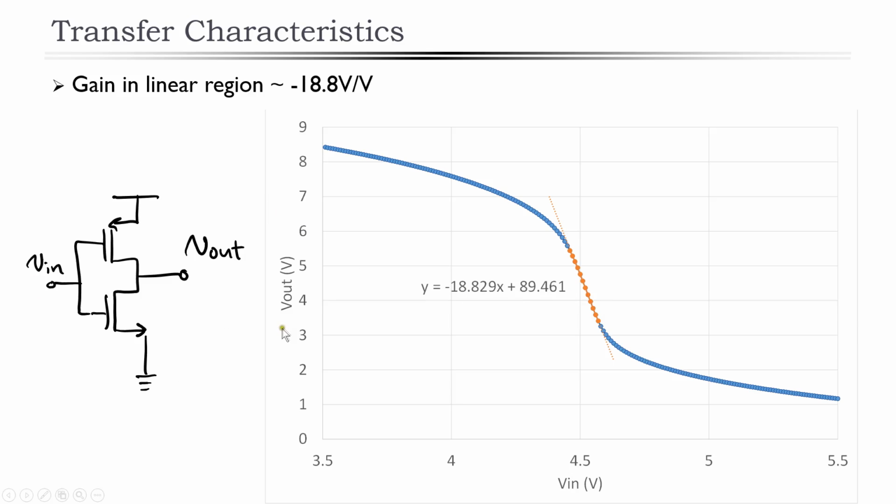And it's also important to point out that the transistors in this inverter go through various regions of operation. So when the input is really small at 0 volts, for example, then the NMOS transistor is completely turned off and the PMOS transistor is in deep triode. That will be all the way at the end of this graph, which we are not showing, where the output would actually be 10 volts. And vice versa, if I increase the input all the way up to 10 volts, then I turn on the NMOS device really hard, deep into triode, and then the PMOS device will be turned off.